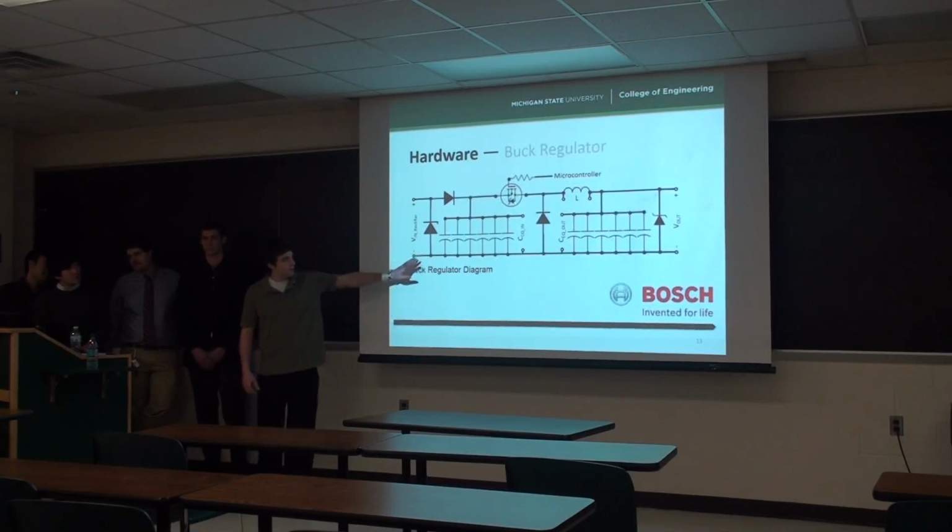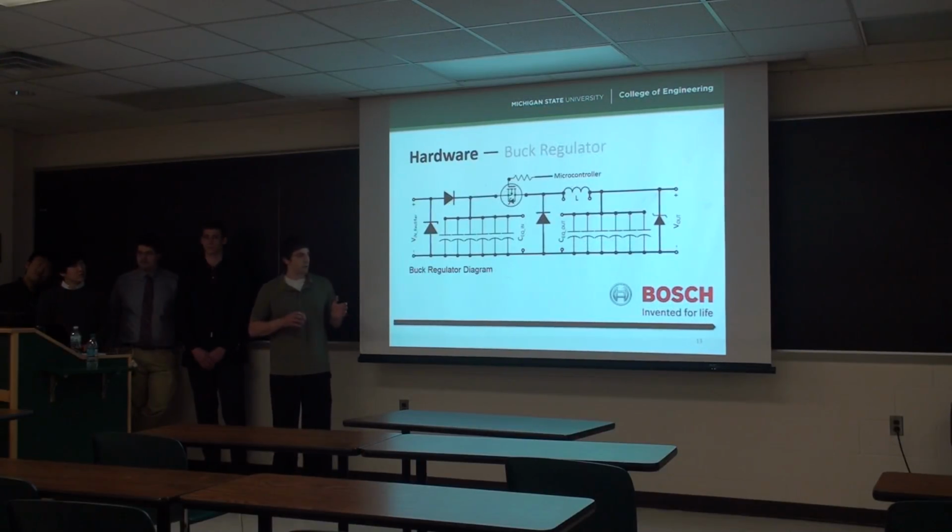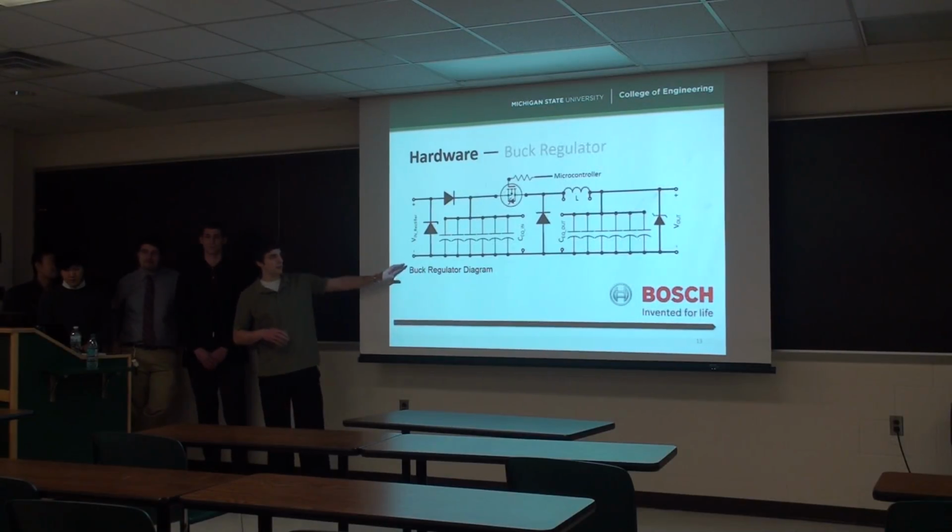The reason why we have arrays of capacitors is because our loads are very unknown. With this setup and all the transients, we have to be able to drop from a voltage around 14 volts to 0 volts and back up to 8 volts all within 4 milliseconds. So obviously any energy storage devices may cause that condition to not occur.